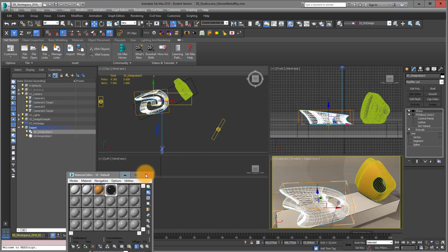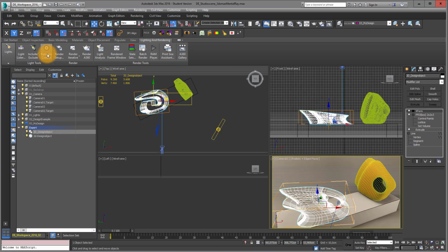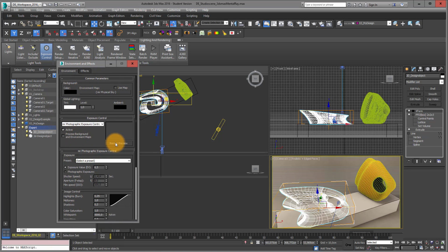And yeah, we are already nearly ready for our first visualization, but like a normal thing with photography, you have to adjust the brightness, you have to adjust the aperture and the exposure control. So what you do is you click on this field render preview. And you see that it could be slightly brighter. I just changed the value to 6, probably even 5.5. Like I said, it's not really about visualization right now.